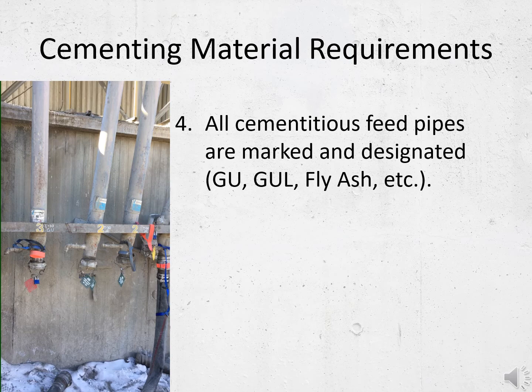Proportioning minimums for both strength and for durability purposes are specific to the cement and supplementary cementing materials used. For example, the minimum replacement rate of one source of fly ash may be quite different from one cement than with another fly ash source. And then, if the fly ash source is kept constant, but the cement source is switched, an adjustment may be necessary in fly ash cement replacement rates to ensure continuous production of strong and durable concrete.